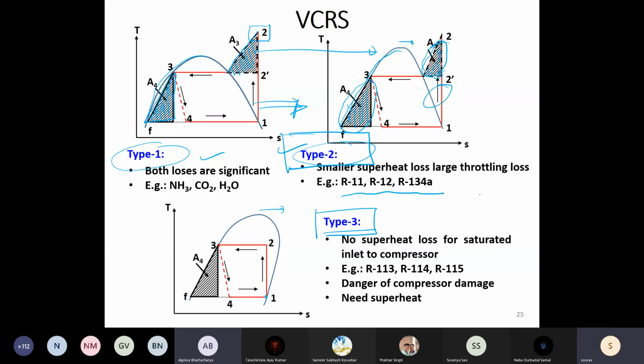So as a homework, what you can do is consider ammonia as one refrigerant, and R134A as the second refrigerant, and check the T2. You need not carry out the entire analysis of the cycle. Assume that the evaporator temperature is 10 degrees. We will not change the operating condition. Condensing temperature is 50 degrees. Condensing temperature is this horizontal line and not T2.